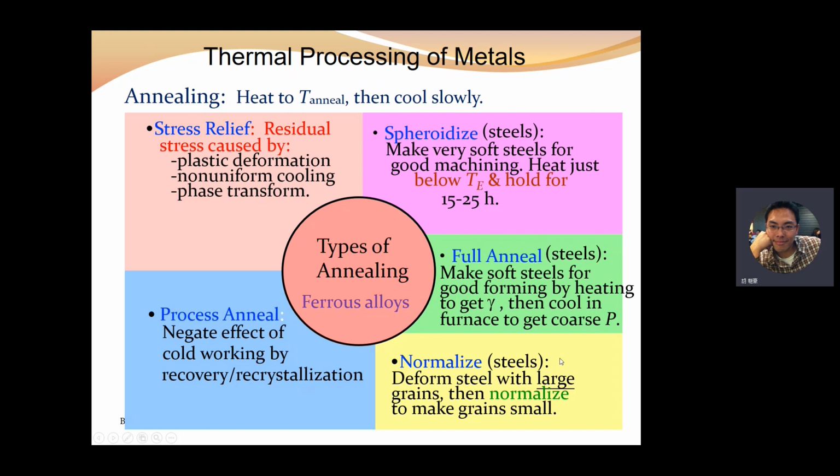Those stresses could be caused by plastic deformation, non-uniform cooling, or phase transformation. Or if we want to make a very soft steel, spheroidizing is the process to make very soft steel with good machinability.